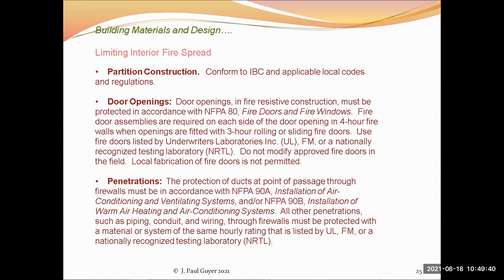Now, I talked about fire resistive construction of interior partitions. And a point to keep in mind is that if a barrier, a wall, is required by code to be of 2-hour fire resistive construction, everything in that wall has to be of 2-hour fire resistive construction. And that includes doors and windows. Now, how do you know who says what the fire resistive rating is of a certain type of wall construction?